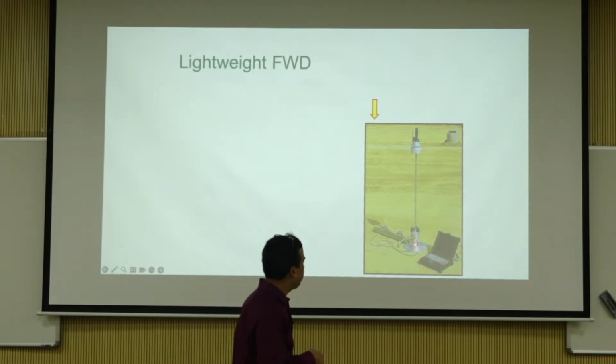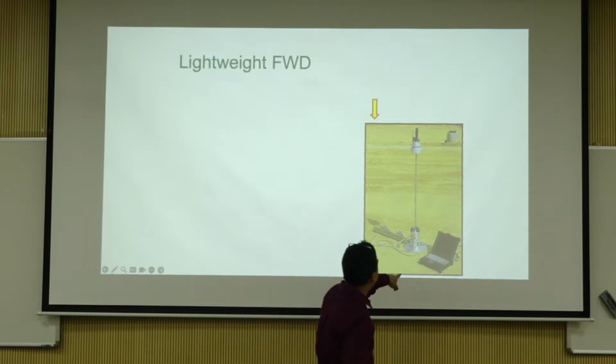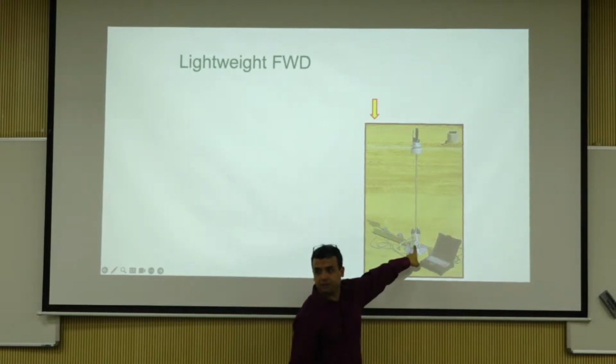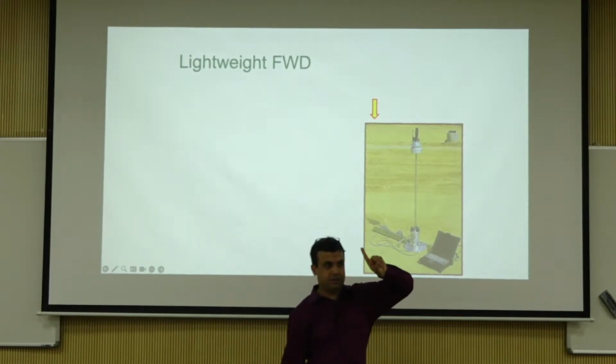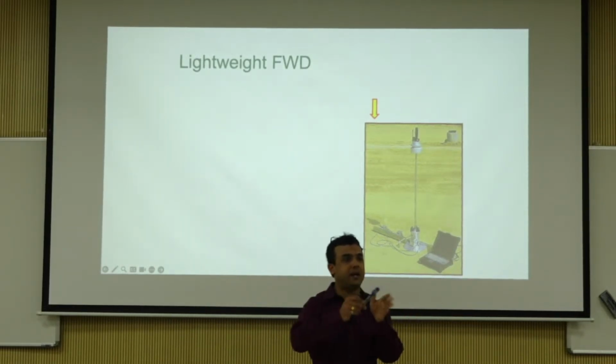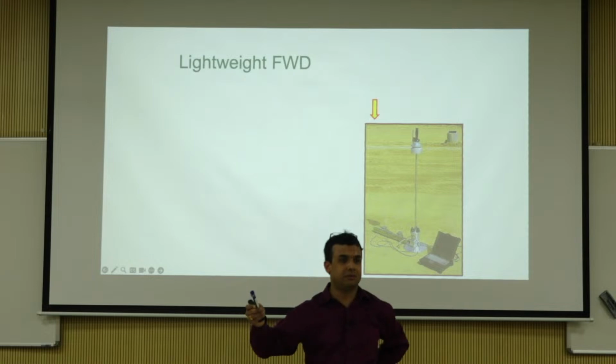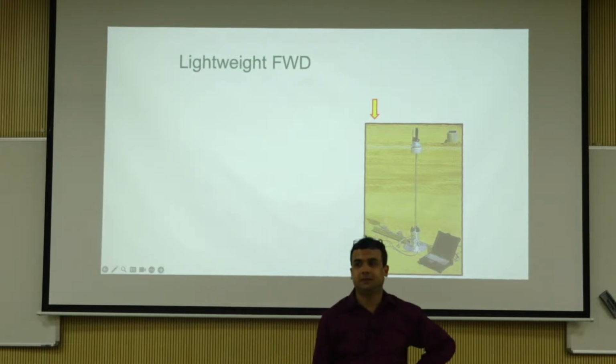But here, you are only talking about central deflection. One. So, can you calculate different modulus for different layers? With one deflection, can you back calculate multiple layer modulus?